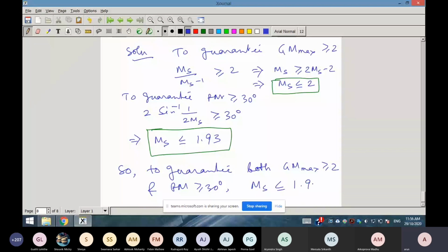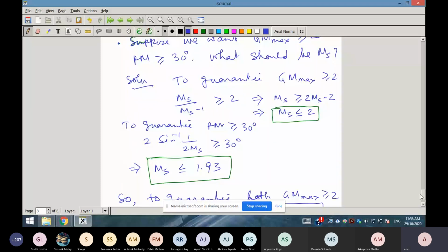So this is the answer. So that means for a good design, your sensitivity norm, that is the infinity norm of the sensitivity function or Ms, should be less than or equal to 2, which will guarantee your gain margin greater than 2, phase margin greater than 30 degree. Even if you make it smaller, then your gain margin will increase, phase margin will increase.